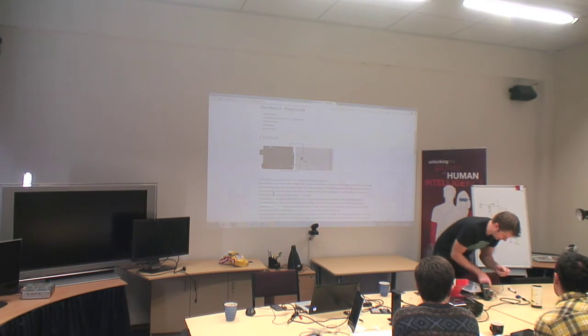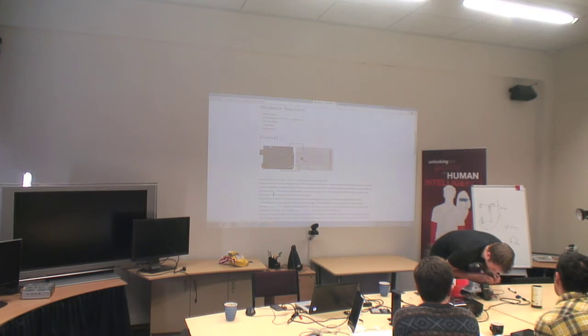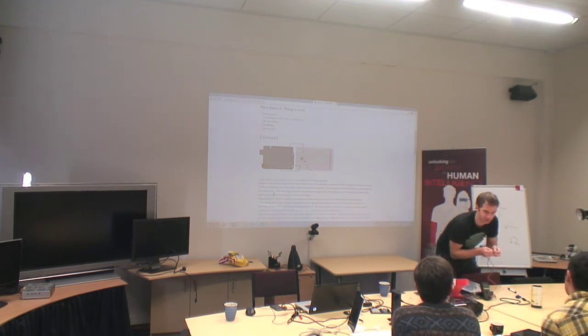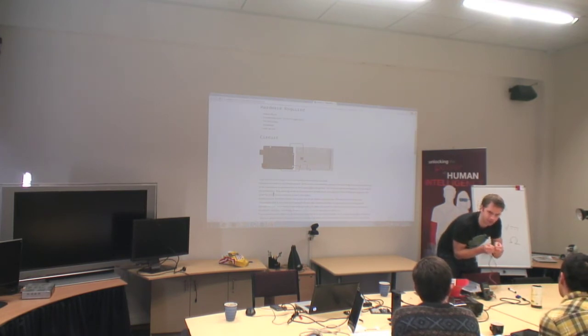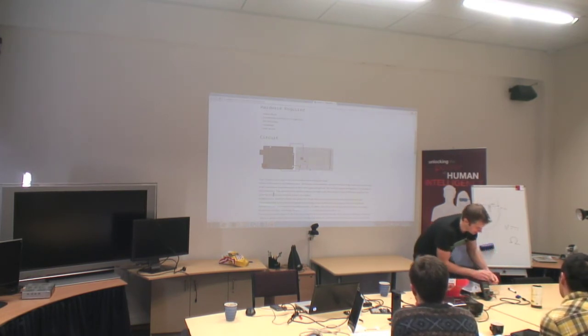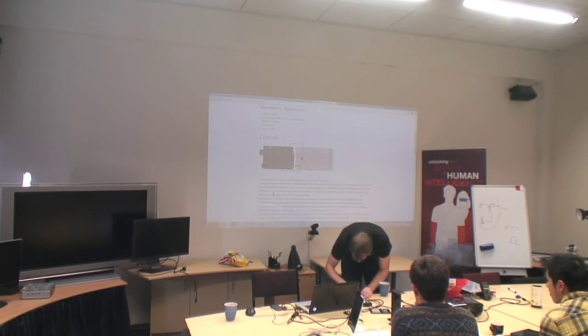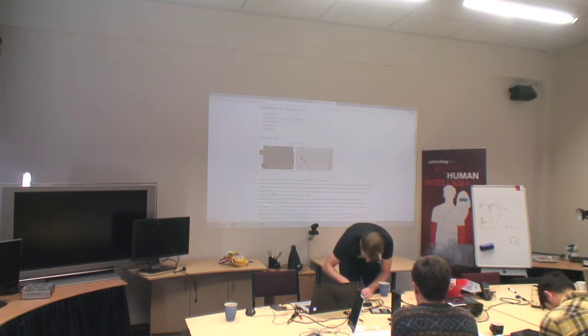This one here is, see there, that's 10, and then it says K ohm on the thing, so it's a little over 10 kilo ohm, and this is a 10 kilo ohm resistor, so that's good. So you just got to make sure you check the number and the units which it uses, so whether it's mega ohms, kilo ohms, or ohms.